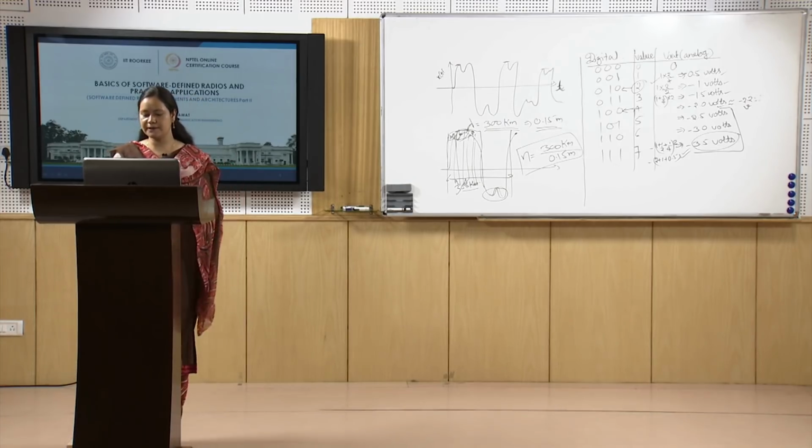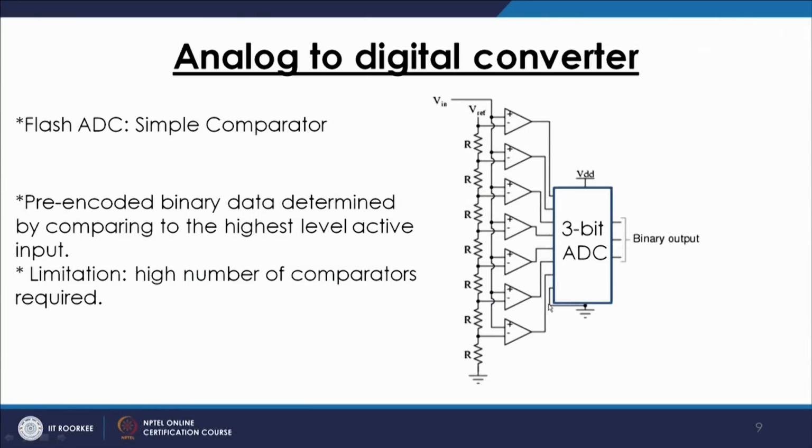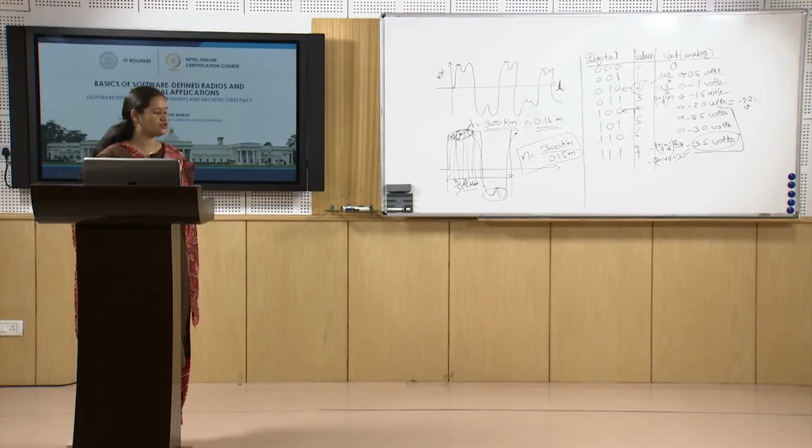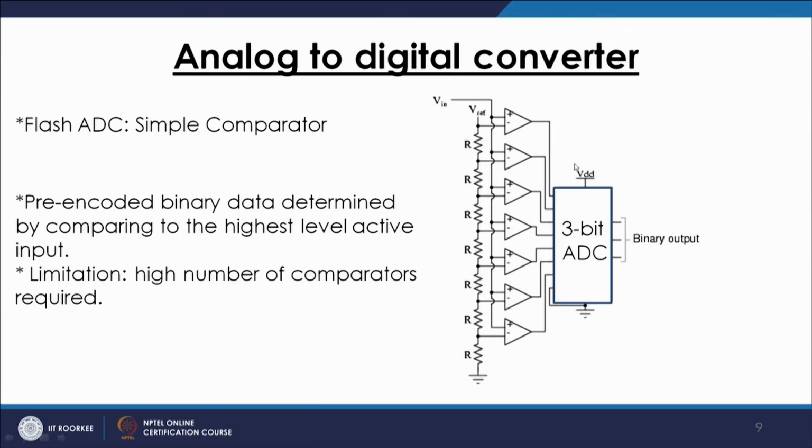So in this ADC, it will be seeing from the least significant bit, because it is dropping all the V reference here, it is the least significant bit. So it will be seeing 0 there, then it will be seeing -1, -1.5, -2, but it will not be giving any output from these, because this reference level is lower than these values.